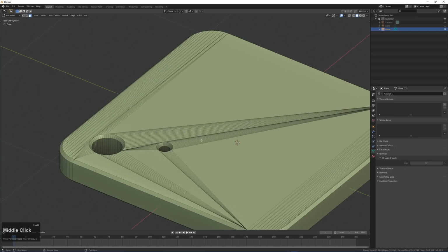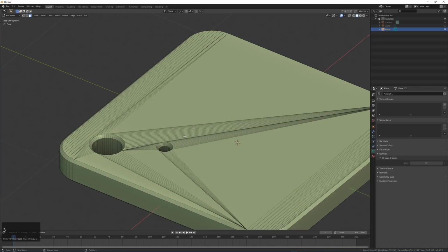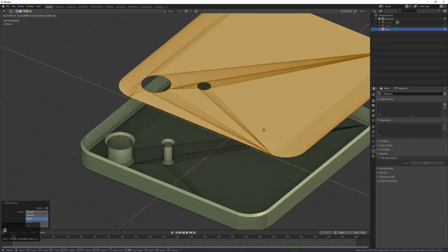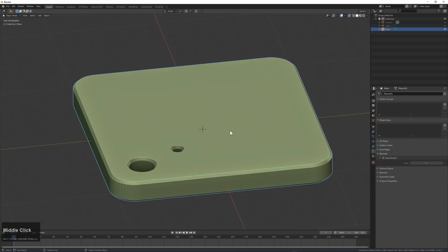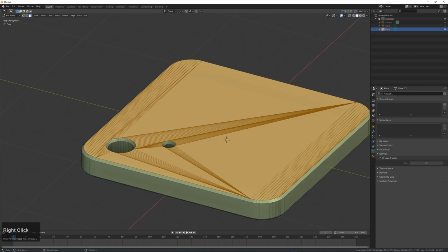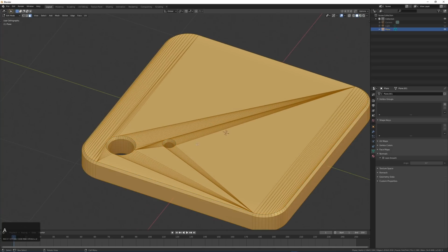So pressing 1 switches you to vertex mode. Pressing 2 puts you in edge mode. And pressing 3 will put you in face mode. The interesting thing about face mode is that if you press L in face mode, it'll select a continuous selection of geometry. And by pressing G and moving my mouse around, you can see that while this is a good looking result, it's not a good result because this mesh is separated, which is kind of rubbish to be honest. So we'll select everything.